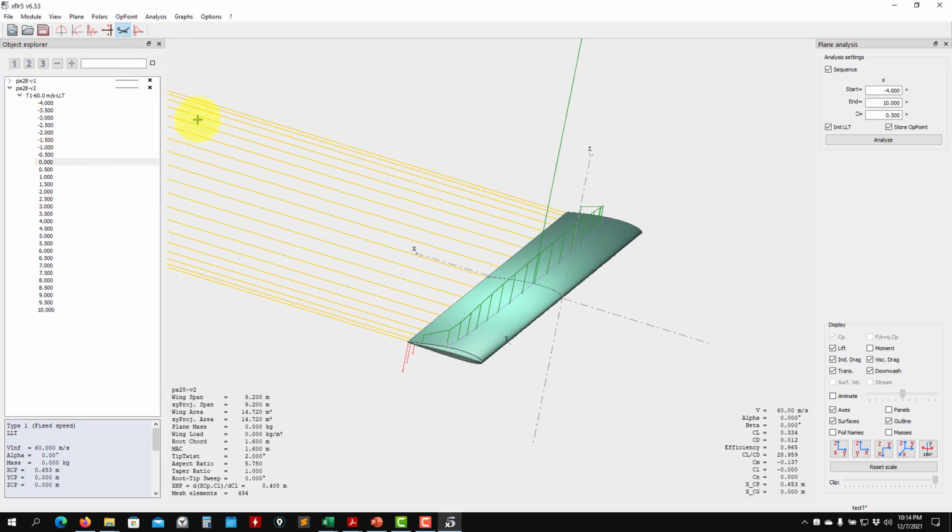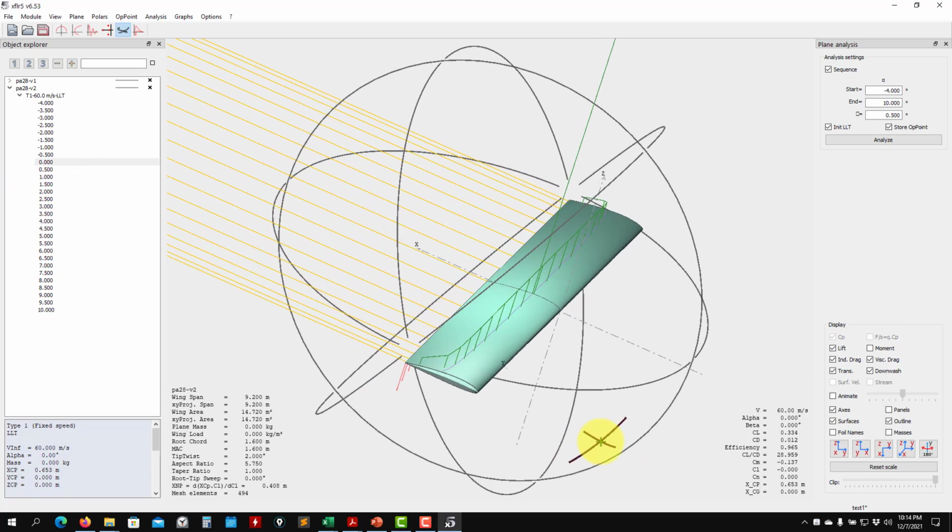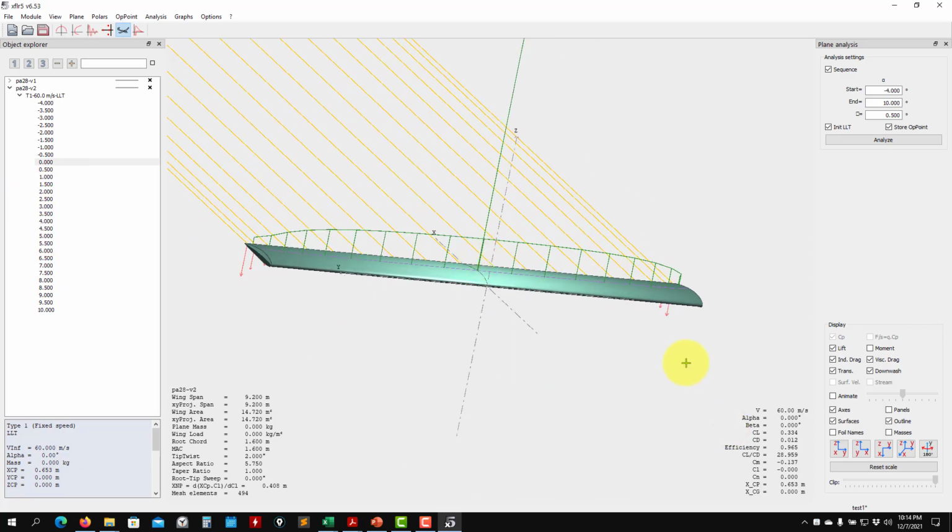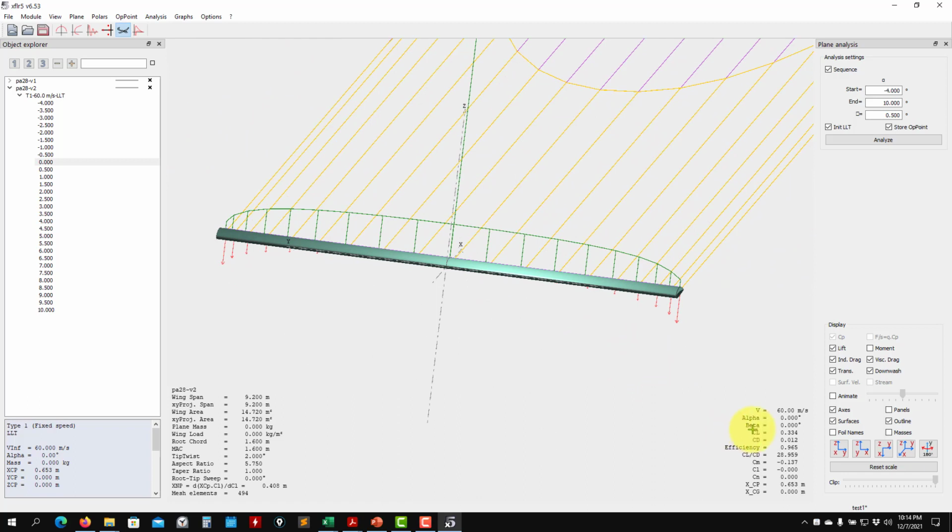So recall that you have all the coefficients, everything, but there is another value that is very important and a good indication of, if you have a good wing, the optimal lift distribution. As you look at here, okay, you have this number here, efficiency. Okay, so this is the wing efficiency. So this is that coefficient that if it is 1, corresponds to the perfect elliptical distribution. Okay, so you want to have this as close as possible to 1.